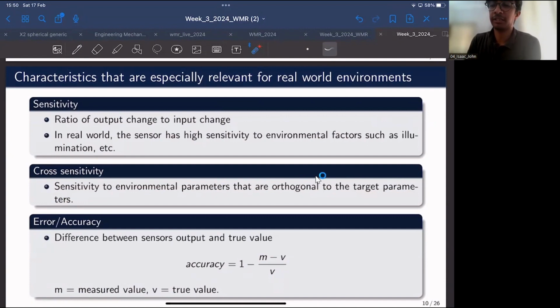If a sensor is measuring using magnetic principles, maybe Hall effect sensors as a proximity sensor, and the robot is in close proximity to some other magnetic field that is nowhere related to its application, its sensitivity may get affected, and more often than not it can lead to an incorrect sensor reading.